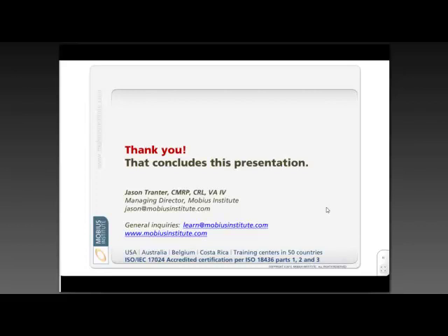So you might say, hey, I would like to monitor this equipment more frequently. Technically, I should, but because of its low criticality, I'm going to take more of a risk and measure it less frequently. I can't afford to measure it as frequently as I would like, and that's just a risk decision. That's just a decision to say I can't justify testing it more frequently. But that's the main thing.